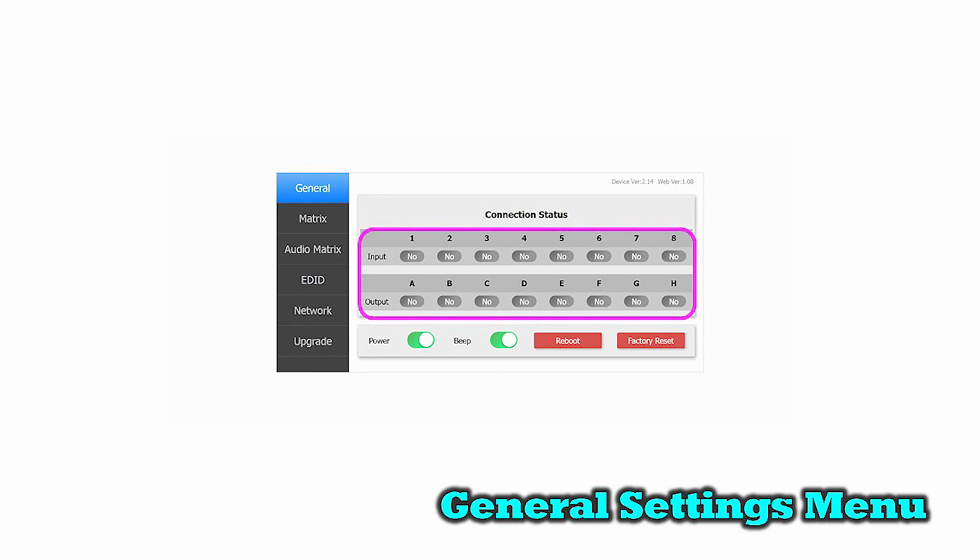You'll be able to see the current connection status of all 8 inputs and outputs to know which devices are currently connected. When a port is active and the Matrix has verified the connection, it will turn green to let you know the input or output is ready to use. On this screen, you have the option of turning off the beep used to indicate button presses for the Matrix. You can also power off the Matrix by using the power slider. This product incorporates a technology called Wake on LAN that also allows you to remotely turn the Matrix back on over the network, which is helpful if you're controlling it from a distance.